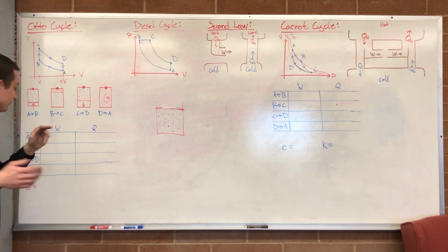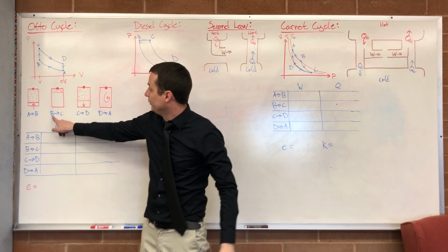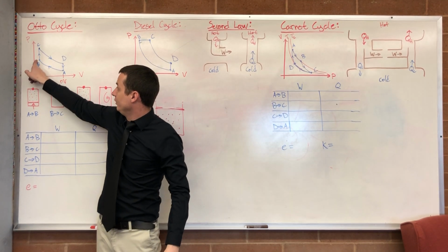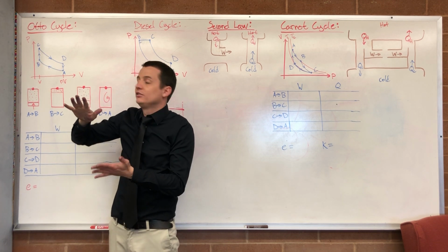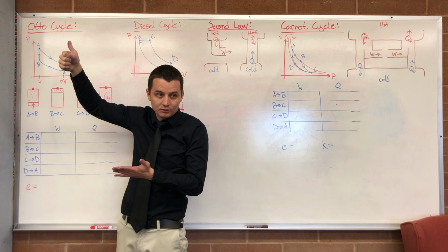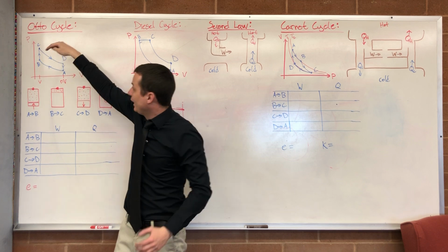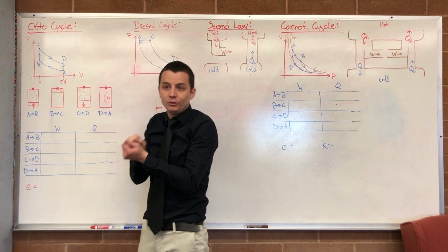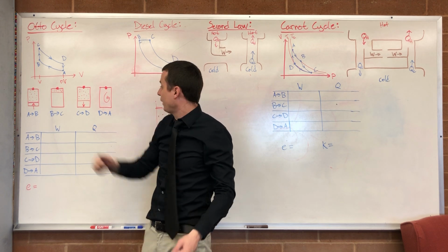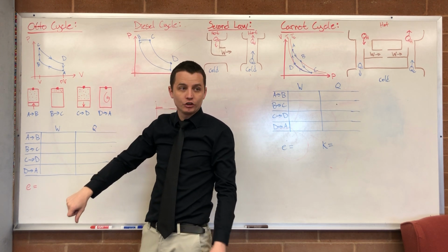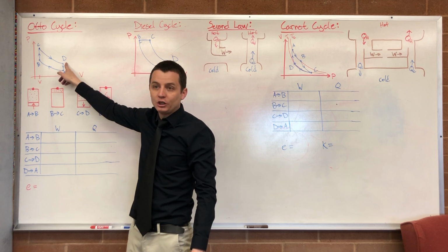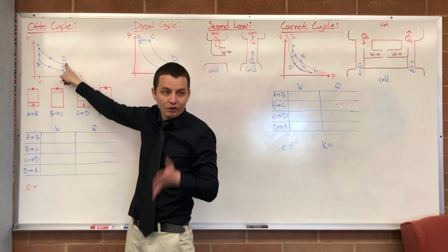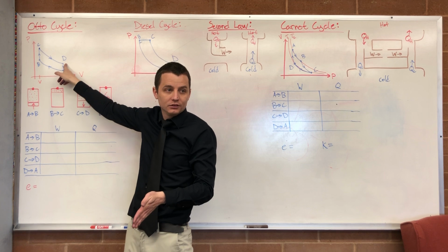Okay, so that's what's happening from B to C. This is a very short interval of time. The gas just explodes, and temperature shoots up inside the piston. And now that it's at that really high temperature, what's it going to do? It's going to push that piston with a lot of power back down. So the piston is now going to expand from C to D. And we call that the power stroke. This is where you get all the work out of your piston.